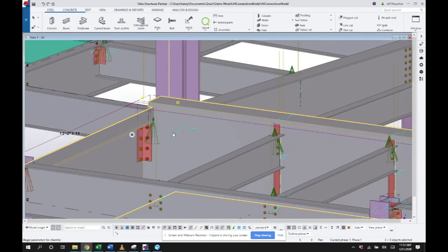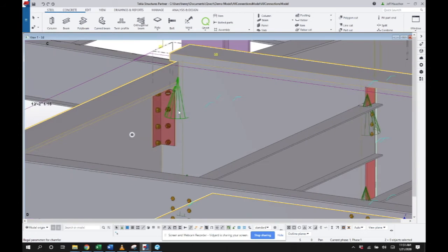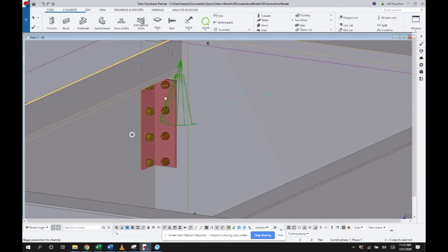And as you can see with optimization, in this case, it's a substantial reduction, very much like the case we saw also at the beginning of this webinar. But with optimization, we typically see 1 to 1.5 bolts per ton in savings. In this particular case, we have 6 fewer bolts to purchase, 2 fewer bolts in the shop to install, 4 fewer bolts in the field, and 12 fewer holes to drill, cut, or punch.